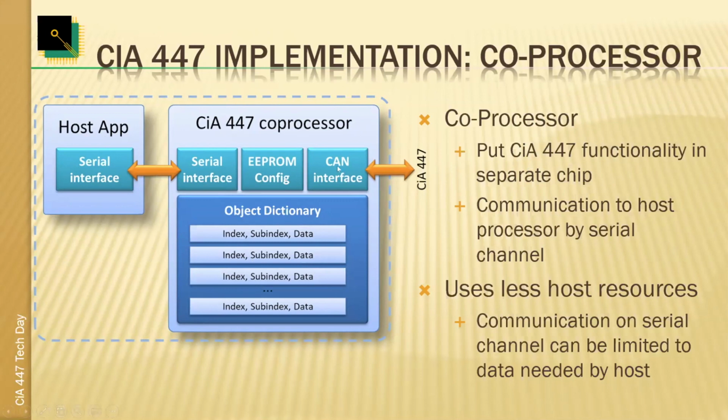And now suddenly this becomes a single standalone running microcontroller unit, and all these challenges that I just mentioned are no longer a challenge towards the host, because the challenge is completely handled by the coprocessor. So even if this host app has a boot up time of several seconds because there's an operating system booting here to the left, well, right after power on, if the configuration is already stored in this coprocessor, it can reply to 447 requests on the CAN side and start immediately running and working.